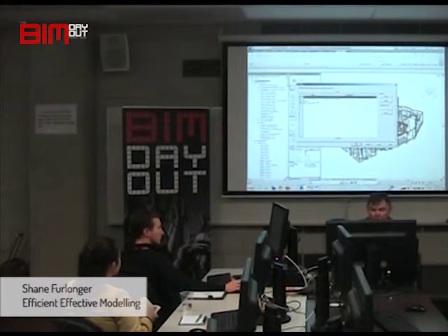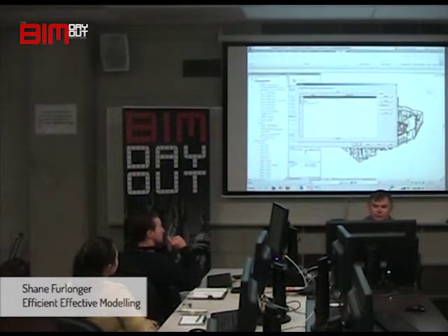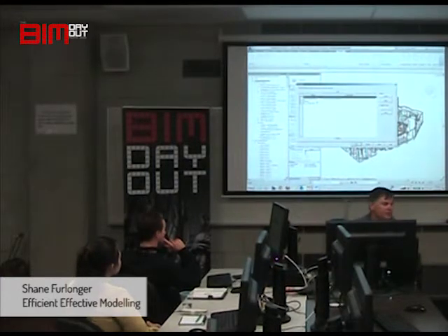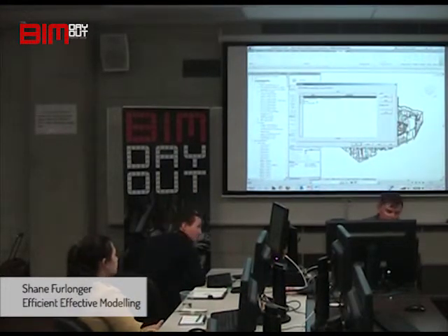You've got to demolish because otherwise your items that you put in this phase will show up in your schedules, which you don't want. Schedules are phase specific. So all you want is your new construction or your existing construction to show up in your schedules.